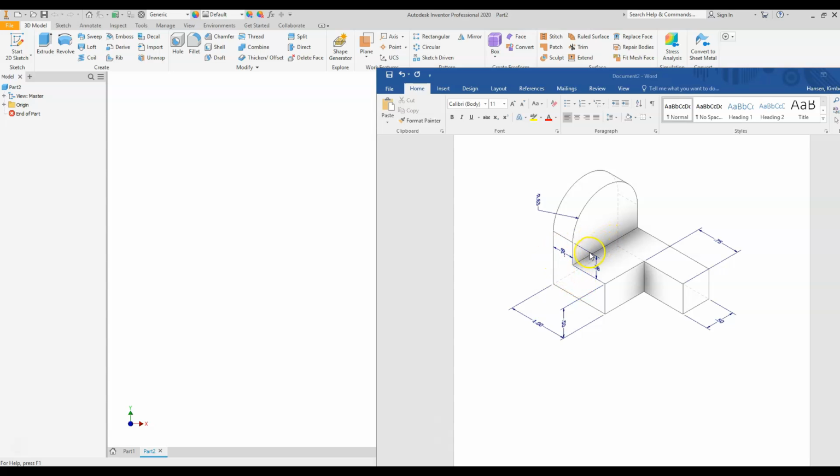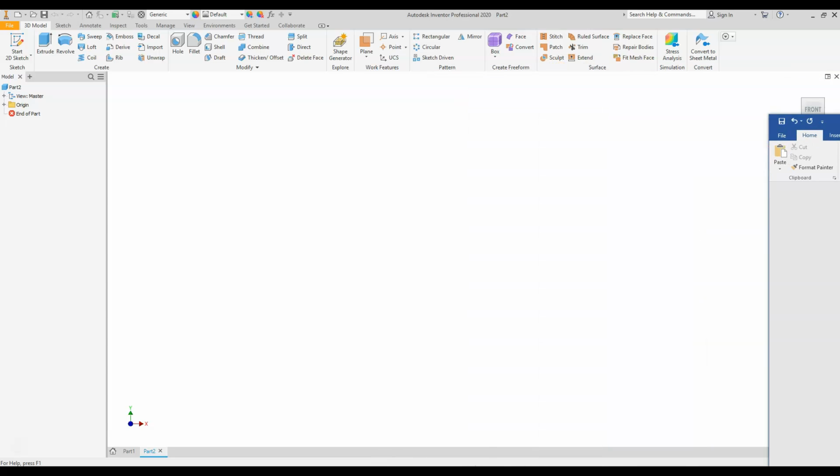I'm not going to start by trying to draw this like a front view or right side or top view. I'm just going to look at the core elements or the geometry in this. First thing I'm going to look at is this bottom piece. It's got a rectangle. It's 1 inch by 1/2 inch. So I'm going to draw this rectangle right here, and then I'm going to add this piece over here on top that's going to be a 3/8 of an inch rectangle. Then I'm going to add the circle part, and then I'm going to come in here and add this to the end. As we get moving through that, we're going to build each one of those components on an existing model or the existing surface that's on here.